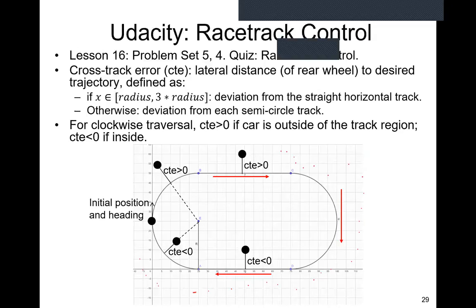But to reduce the error, you need to adjust the vehicle heading in the process, and it's a nonlinear equation. If you have two objectives, you should put a weight on each objective. But in this case, the total error is actually a function of both factors. One is the heading, one is the distance to the center of the lane.